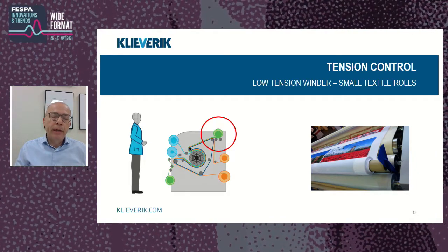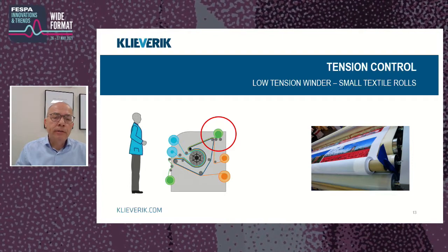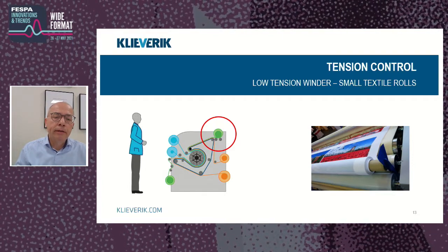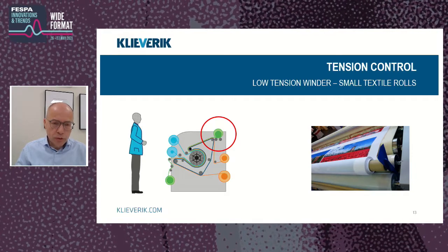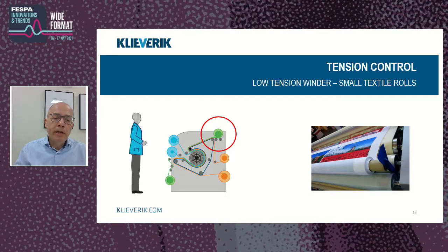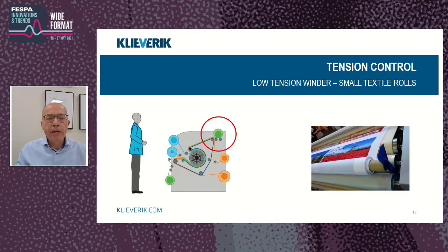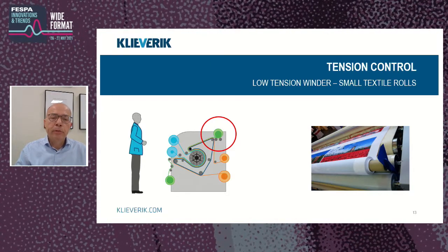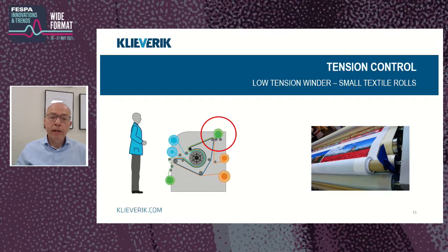The motor, again, you can adjust, so you can put a little bit initially slightly higher speed compared to the machine. You get a nice compact roll, good tension, which is perfect for a cutting machine. But if you have sensitive material, you also can put it initially to a minus setting, and you get, similar to the infeed, a very slack, tension-free winding.